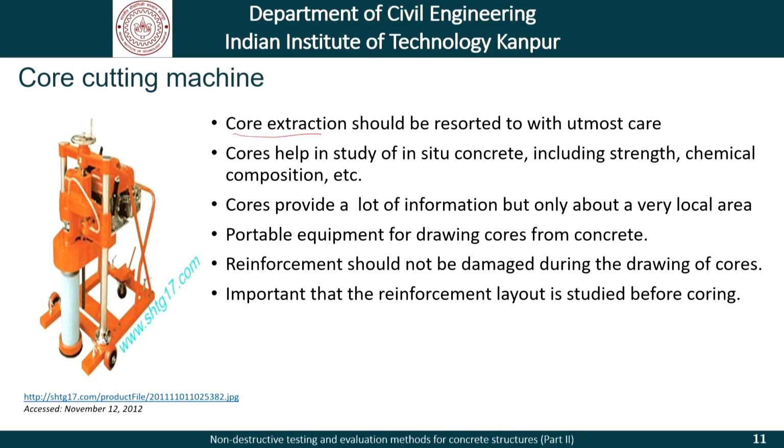But core extraction should be resorted to with utmost care, because in any concrete structure, no manager will allow indiscriminate extraction of concrete cores. Cores, of course, can prove to be an invaluable source to provide information about different aspects, and they help us study the in situ concrete in terms of its strength, chemical composition, and so on. They provide a lot of information, but again, from a very local area.